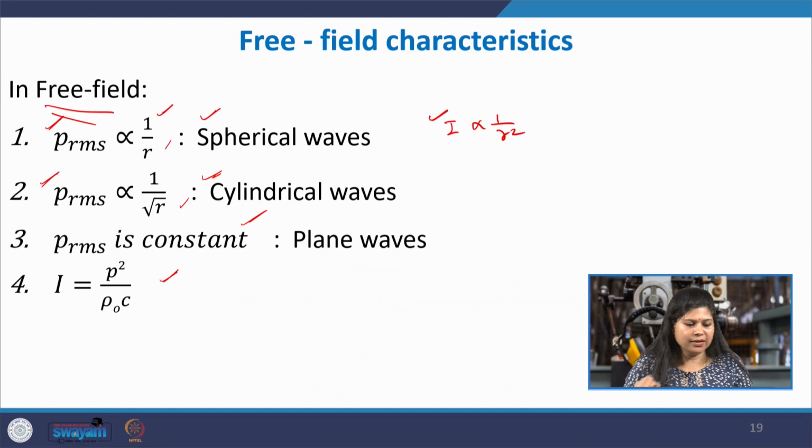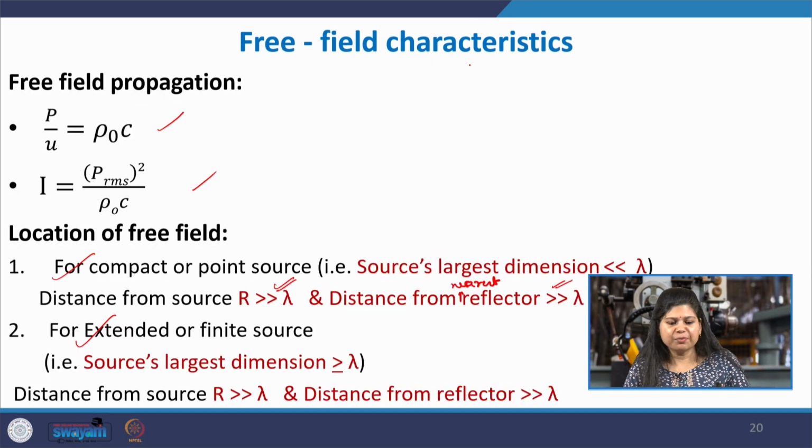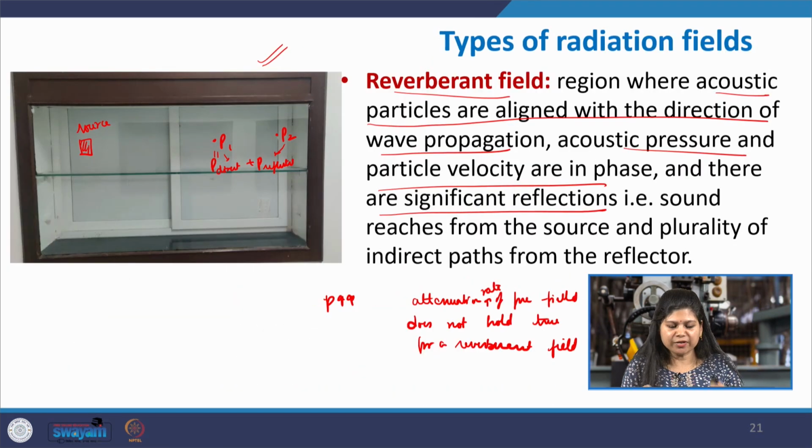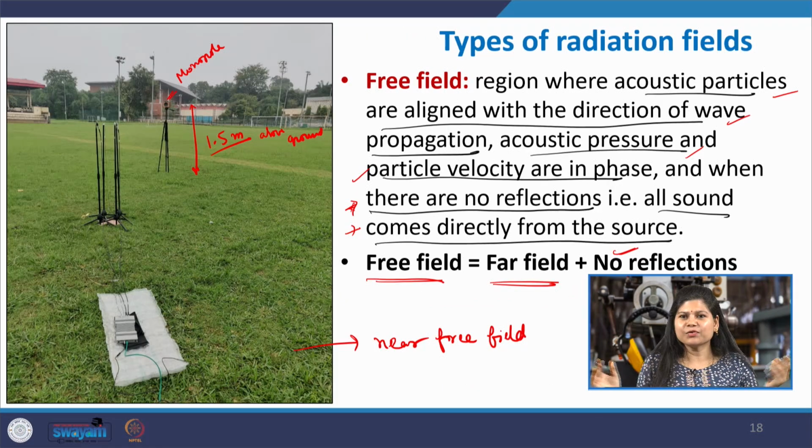And the pressure amplifies because it is both the direct pressure coming from the source, plus the indirect pressure coming from the reflected pathway. So, overall the acoustic pressure amplifies, and that is why you observe that, suppose you are moving around in, let us say, I will again come back to that football stadium, a very large football stadium or very large open field, and when the players are playing and shouting at each other, still the noise level is down.